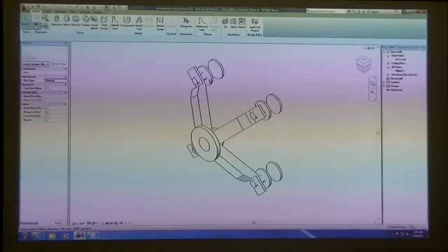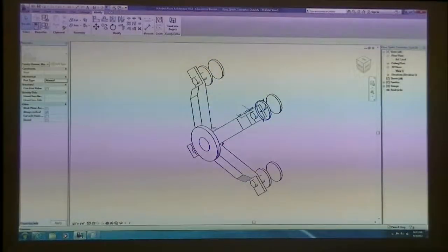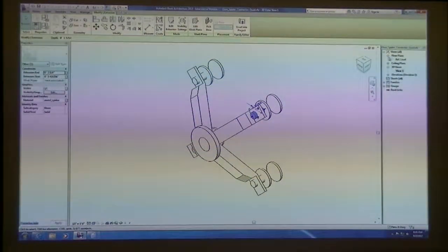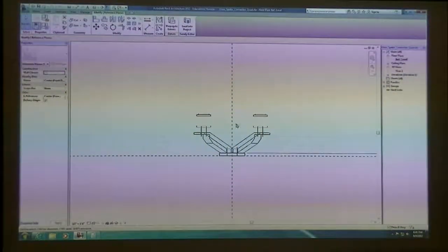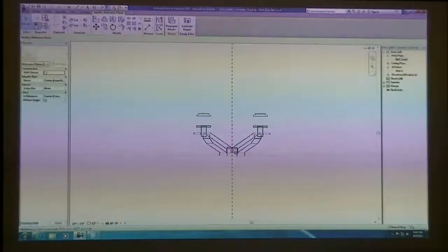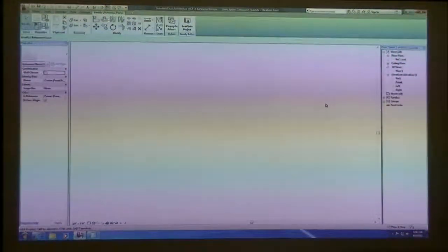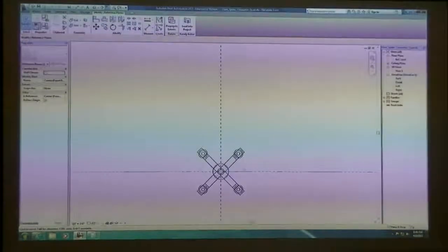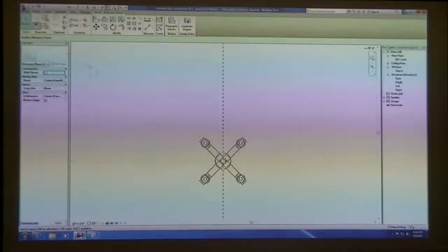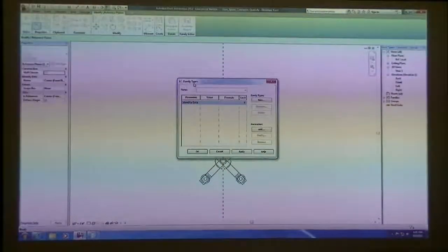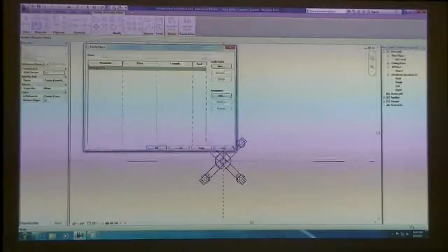And it's basically just a set of extrusions, all these different pieces and parts that were put together based on, in a floor plan, there's just one reference plane, have this centered about the two reference planes. And then in elevation, it's just again centered at that location as well. There's no parameters set. So if we actually look at the family types, there's no particular parameters.